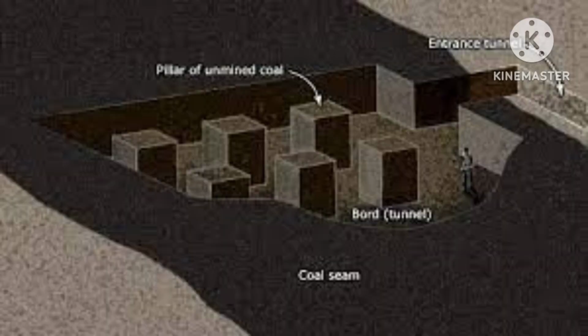The Phase2 results show, first of all, horizontal displacements, vertical displacements, maximum shear stresses, maximum shear strain, differential stresses, and volumetric strain. After this, we did some calculations for the room and pillar mining method that is used in potash salt mining in our design mine.